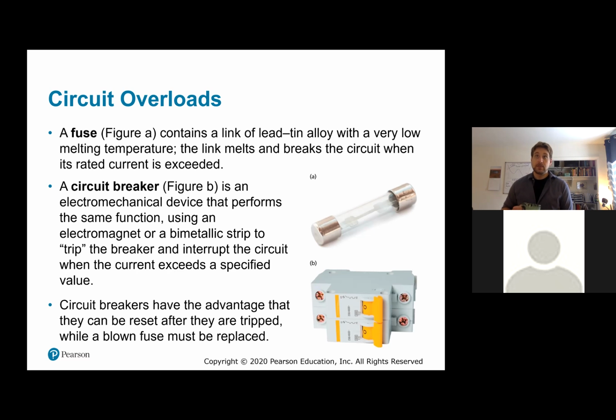The multimeters, the digital voltage, current, and ohm meters in the lab on campus have fuses inside. If you try to measure too much current, it'll blow the fuse instead of frying the electronics. So if you find a voltmeter that doesn't quite work, maybe that's it, and the fuse has to be replaced. A circuit breaker, like those in houses nowadays, has the advantage that we can reset it after it's been tripped.